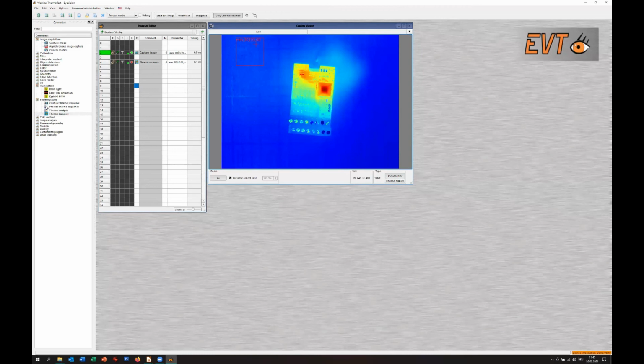You need a camera which is active or can detect the wavelengths you are using, based on the emission coefficient of the surface you are looking for. There are tables on the internet. If you go to wiki emission coefficient for thermal cameras, you will find them, and then you will also see